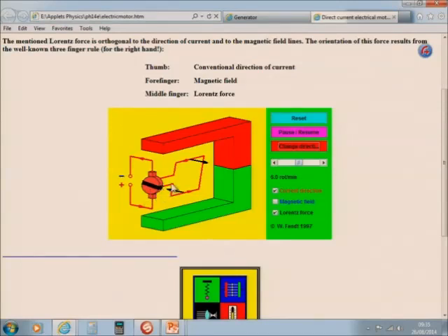It just makes sure that there's no short circuit between those 2 brushes, so that the electricity has to take this route. It will go in there, it goes through this bottom half of the split ring, then it goes into the winding, and it can only go out on the top part through that split ring, through the brush, and my circuit is complete. So that is a component which we call the split ring. What we will also find there now is that I've got my magnet. That is my last part. And then we've gone through all the components.